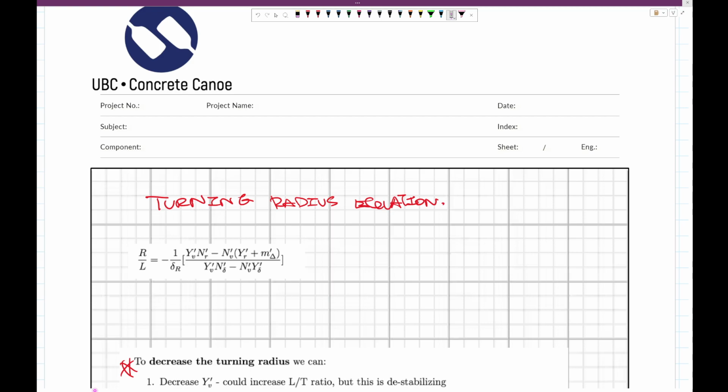is our rotation mostly controlled by the rudder in a traditional boat, which is at the back? We're going to have contributions of forces all along the boat, at the front and also at the back. So we are actually not likely going to have some type of consistent turning arc, which is the 3rd phase of your turn. But nevertheless, this turning radius is basically linked to that constant turning radius.